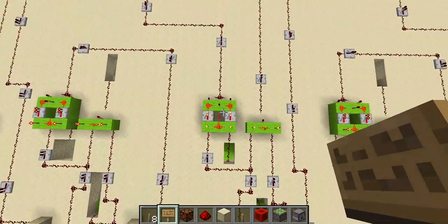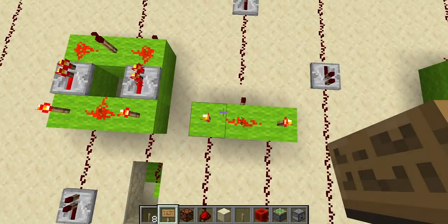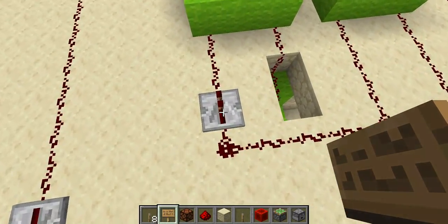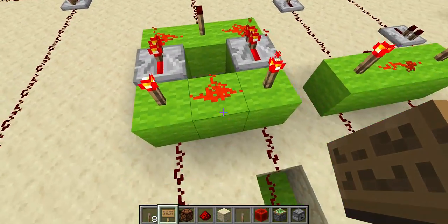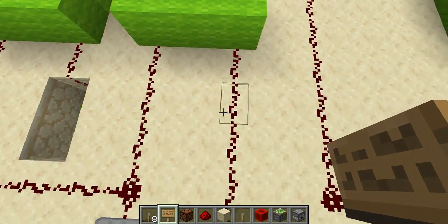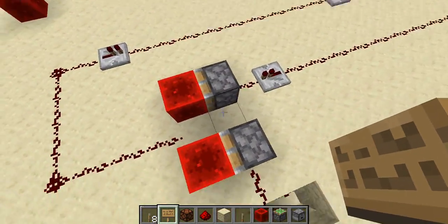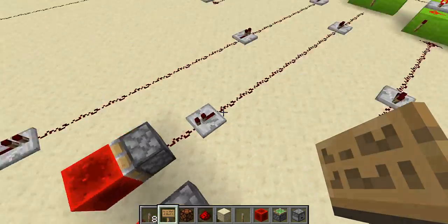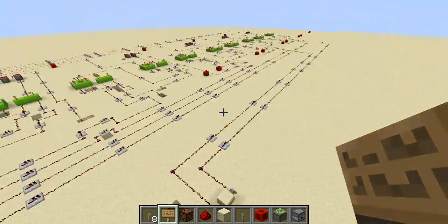What you have is 3 gates in each adder. It's an XOR gate, and an XOR gate, its function is to turn on only when one of the inputs are on. It's an exclusive OR. The gate on the right is an AND gate. That turns on when both of the inputs are on and only when both are on. And that's an OR gate, which turns on when either or both of the inputs are on. And those are the 3 logic gates in each adder.